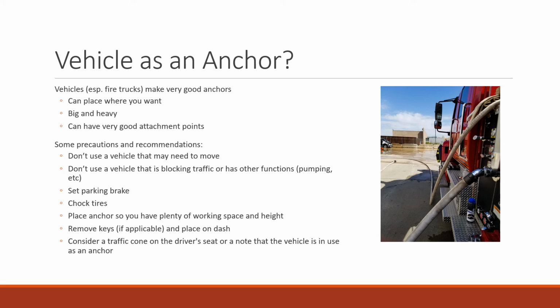When you're using a rig as an anchor, set the parking brake. Even if you don't normally set the parking brake on stuff, set the parking brake. Chock the tires. Point the tires away from the hill so that they're angled away and you have more friction going on. Make sure you have plenty of working space and height.